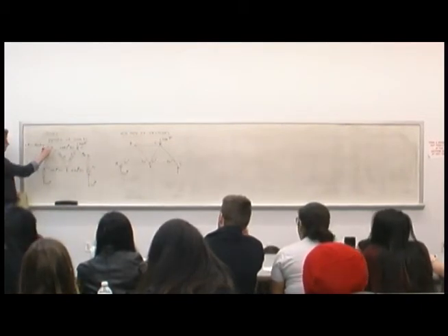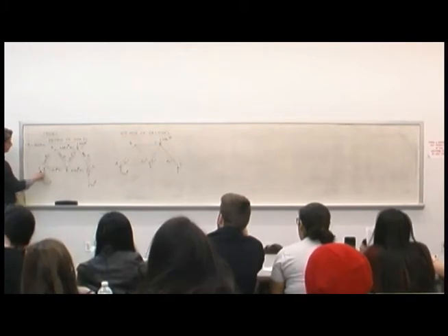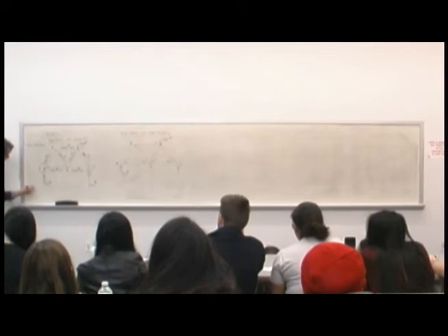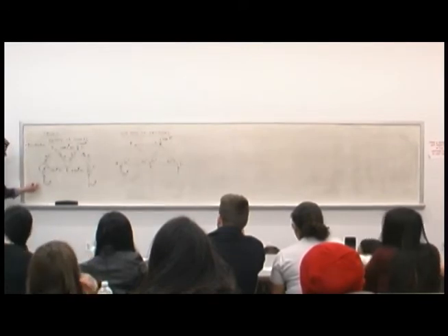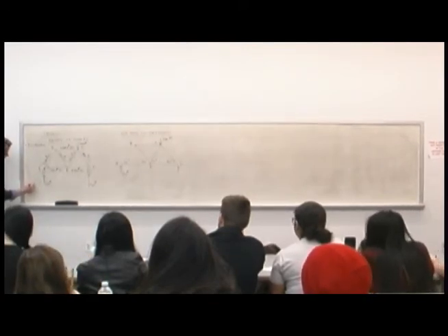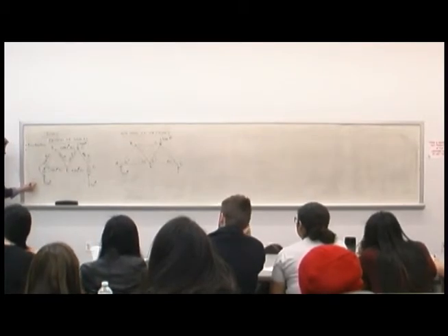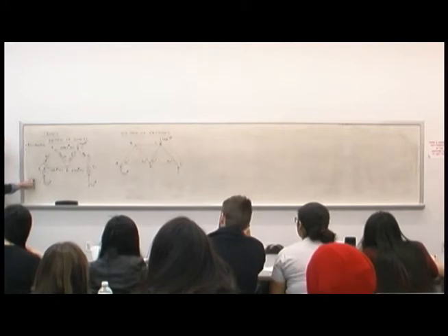In the method of joints, we look at a joint, take a free body diagram and balance it, and we care about the components coming into the node. So the diagonal member, in this case, we get a component, another component, and we balance it and solve for the unknowns.